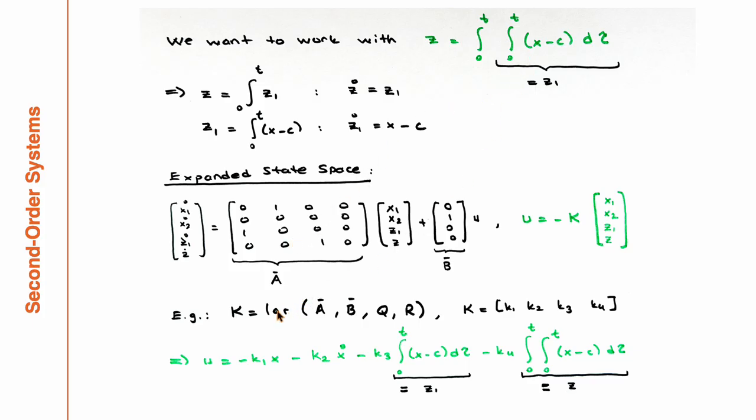So again, you can use pole placement or linear quadratic regulator, assuming the expanded A bar and B bar pair is controllable. Just plugging it in, it will give you some gain. And this is how your controller will look. You have derivative, proportional, integral, so kind of a PID flavor plus double integrator that is more than a PID.